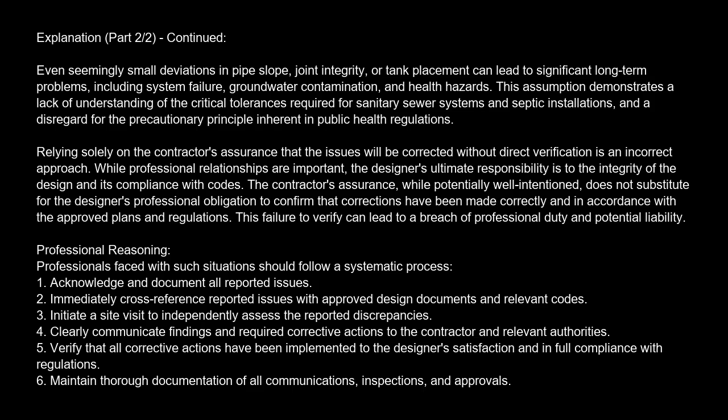Even seemingly small deviations in pipe slope, joint integrity, or tank placement can lead to significant long-term problems, including system failure, groundwater contamination, and health hazards. This assumption demonstrates a lack of understanding of the critical tolerances required for sanitary sewer systems and septic installations, and a disregard for the precautionary principle inherent in public health regulations.